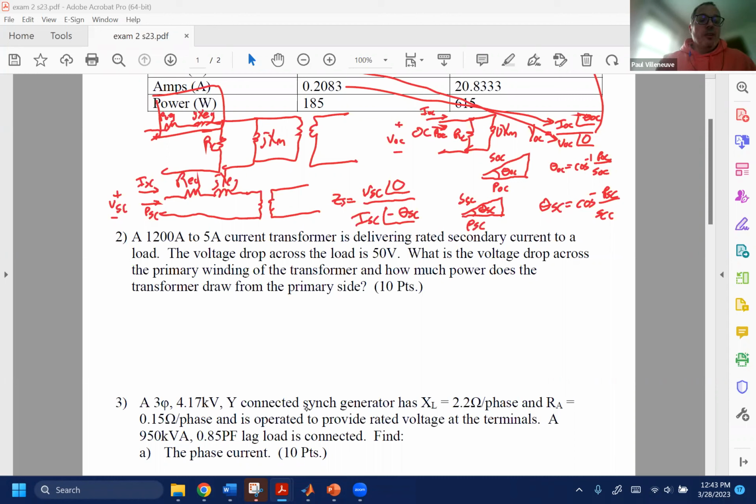One of the things we do is, if we have 1200 amps going through a transmission line, for example, we can monitor the current through there using essentially just a regular old transformer. It's twisted a little bit, but we put this current transformer on there, and its purpose is to step down 1200 amps to the corresponding secondary amount, which in North America is typically 5 amps.